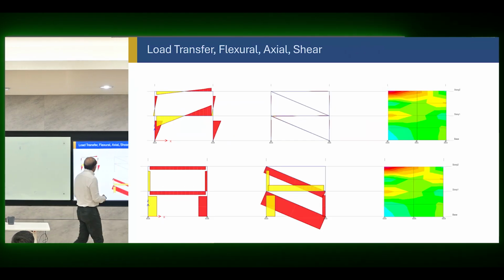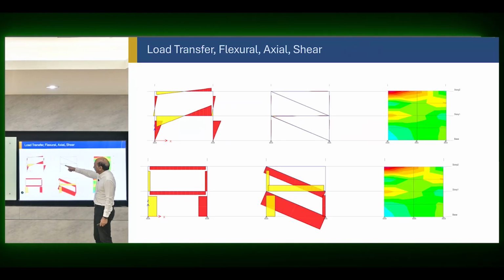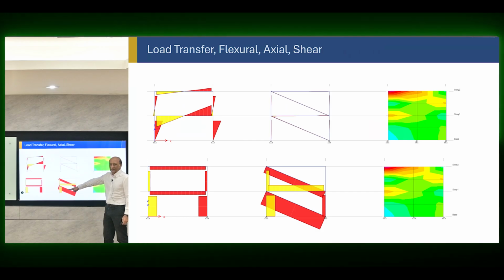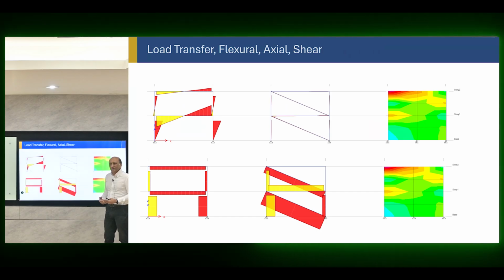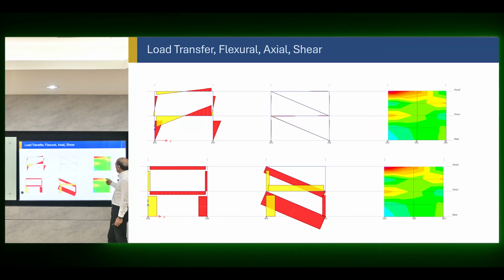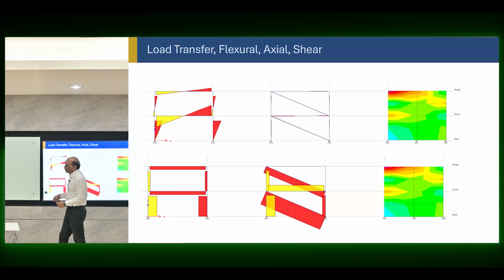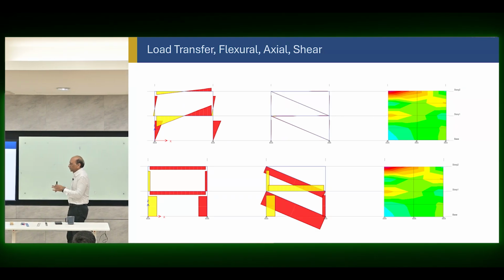If you look at the bending moments, there's a very large bending moment here, almost no bending moment here, because all of the force is taken by the diagonal forces. That means we converted the lateral force into axial forces, not bending. Bending is reduced, and that's why our displacements are reduced, because axial stiffness is generally more efficient than flexural stiffness in deformation. And then shear, if you have a perfect shear panel, it's fantastic. It doesn't deform much at all. It's almost rigid in a certain proportion.